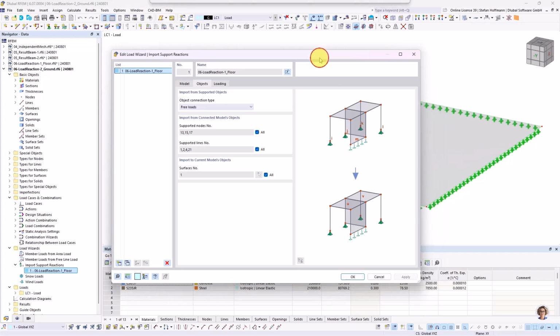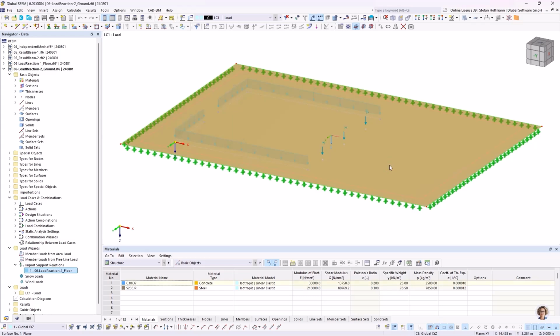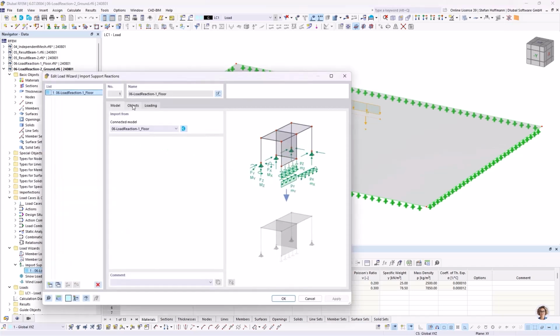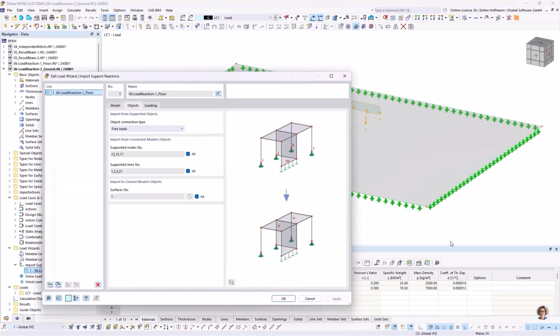the forces. Just imagine if you have a floor laying in here and also define a second surface, all these forces will penetrate into the global Z direction, whatever they can penetrate, and this may double the load if you have the same surface down below. So if the construct of the part is only standing on one surface, you have to disable the all check and assign these loads to the corresponding surface.